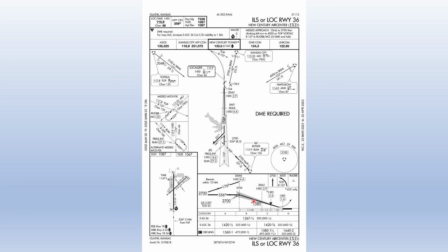You can see those are marked with asterisks there, and it says over on the side that this is for the localizer approach only. You don't need to worry about those if you're shooting the ILS. And then the missed approach point, which is the end of the runway and has a DME distance from the localizer transmitter, is also something we typically only use on the localizer approach.